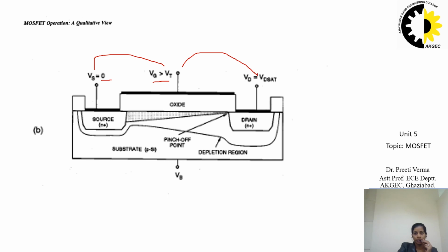If you see here between Vg and Vd, this difference will be lesser to attract the negative charges from the surface, from the p-type substrate. For that reason, the charges collected towards the side of source are more than that on the drain side, and here the depletion region is broader towards the drain side due to more reverse biasing at the drain terminal.